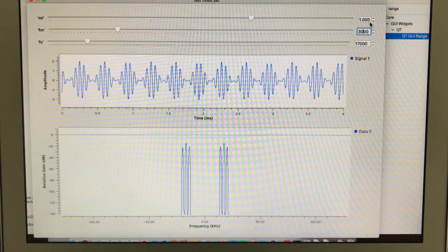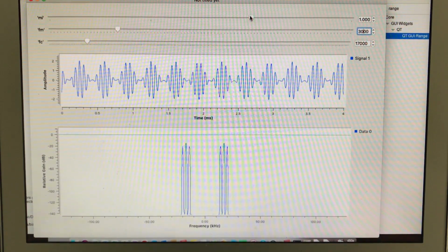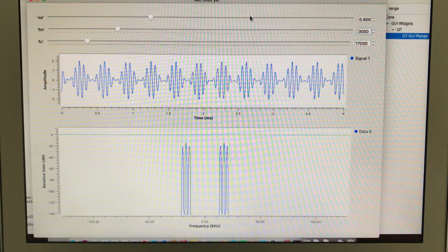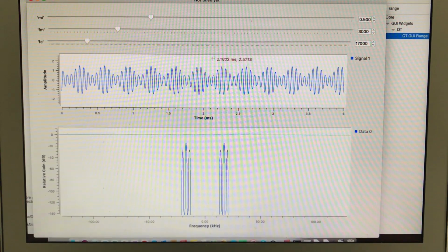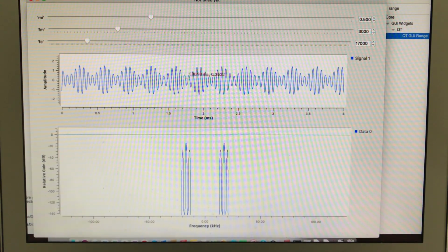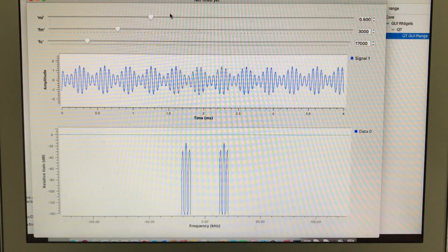Now let's try to under-modulate our system by just changing the modulation index. When I change the modulation index, as you can see, this is no more in the middle, no more 0. This is some value, whatever that value is, 0.5. So 1 minus 0.5, 1 plus 0.5, when you divide this. So this is at 0.5, a 50% modulated signal.